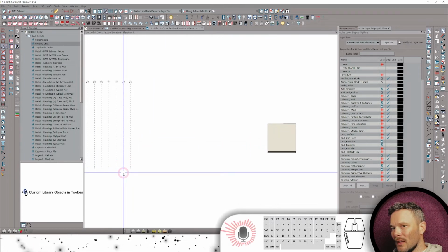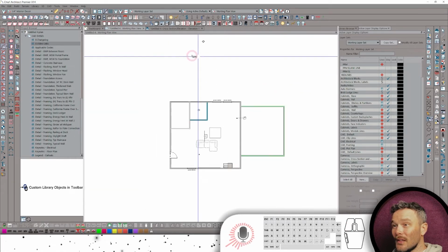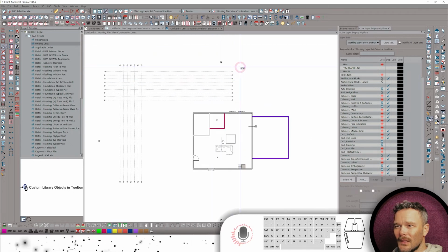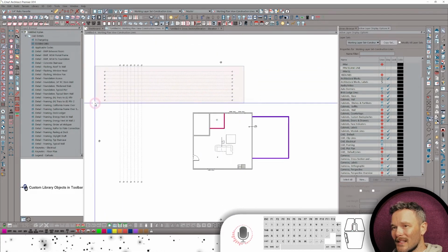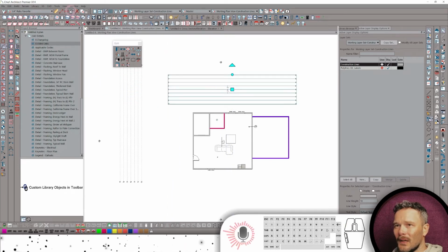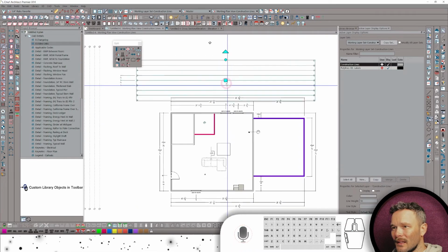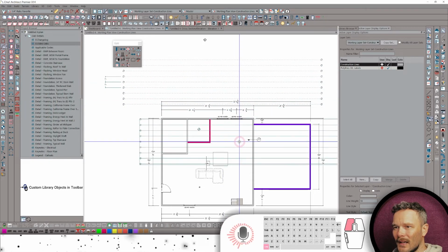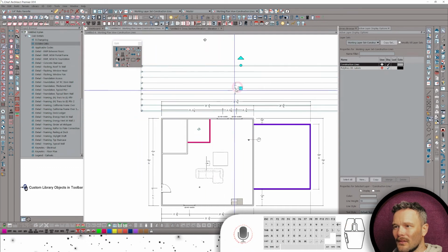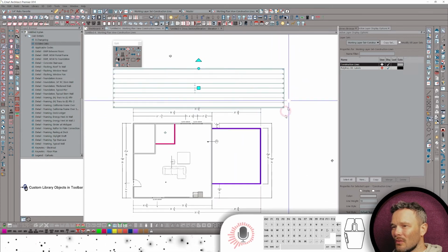And I only show a call out on the top side. The call outs are actually our construction lines. I did want to show you just how I use those construction lines before we close out. Getting into these construction lines, I like to use the extend and trim tools to drop my construction lines in here so that if I'm using my 1/4 inch all exterior dimensions, I want to make sure that these construction lines are outside of those dimension lines, right? So I want to line them up on one side so that they're just outside of that dimension string. And then on the right side, sometimes I need to shorten this or extend this.